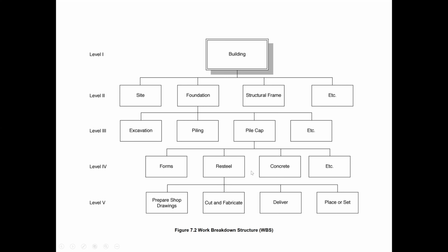So this is what he said before, that you cannot connect piling with re-steel, because piling is a different work. Piling could be bore piling or spun piling. Piling has its own reinforcement, tremie pipe and casting concrete. If it's a bore piling, we have to drill the hole and maintain the hole with bentonite slurry, then we put the steel cage inside, and we cast concrete by tremie pipe. So piling is separate, and pile cap is a separate thing.